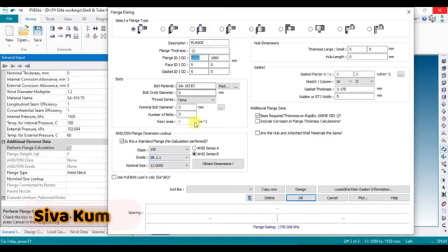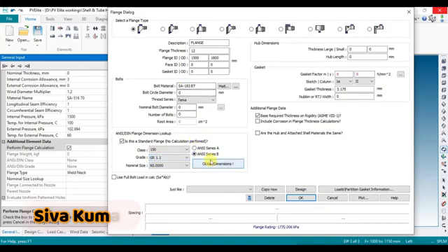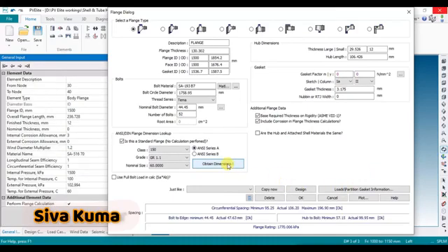We enter this ID 1500, so that 60 inches will be there. NC series A we choose, and then include corrosion and flange thickness. So the hub diameters will be automatically calculated. Now click update dimension. So here you see all the dimensions have been automatically calculated, and here you see everything is okay, everything has passed.